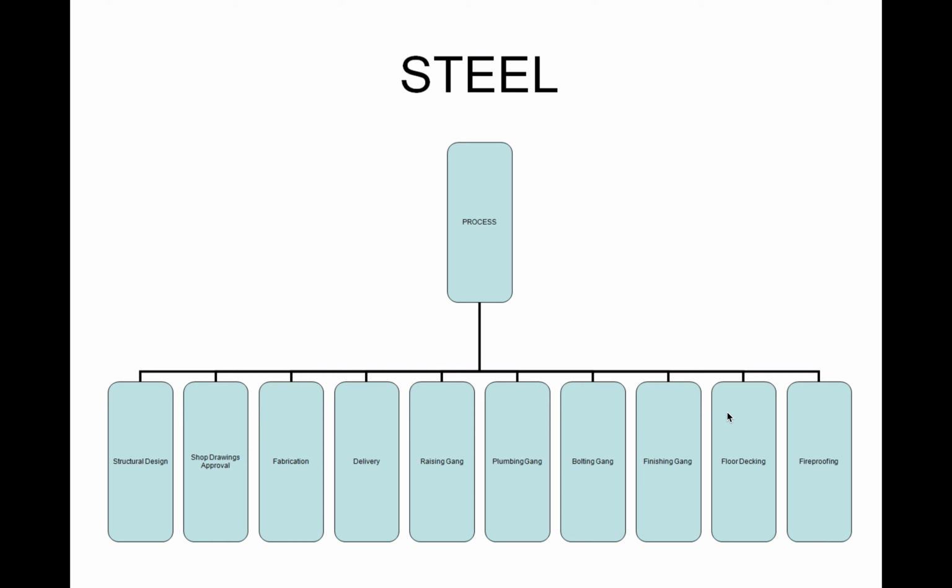From those shop drawings, they go through a fabrication process. What they use in most facilities now is what they call CNC drilling, which is a computerized drilling program where you punch in all the information, you put the steel up there, and it basically will drill these holes in the exact locations as per the drawing. They're linked into the drawings. So in essence, you shouldn't have an issue. The only time I see errors in those situations is where the CAD file or the drawing is put in a mirrored fashion, as a copy and paste by somebody on the CAD floor, and then it comes in and things are in kind of the opposite location as far as drill holes for your bolts.